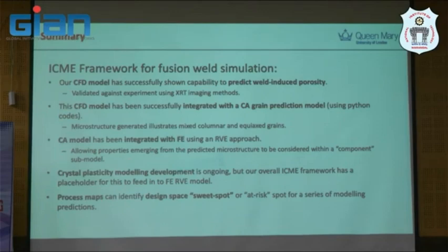And the process map that I showed you, this is something we as engineers want to have, based on crack criteria, based on whatsoever. For me, probably based on porosity, because we believe it's going to be based on microstructure prediction. This is something that a model can do, probably rapidly generating the data compared to experiment and less expensive. Thinking about Ti-6Al-4V material, quite an expensive material, you're not going to produce thousands of conditions to have the map. But hopefully we can have the model, and probably in the future we may use quantum computing to accelerate the calculation somehow. I don't know.